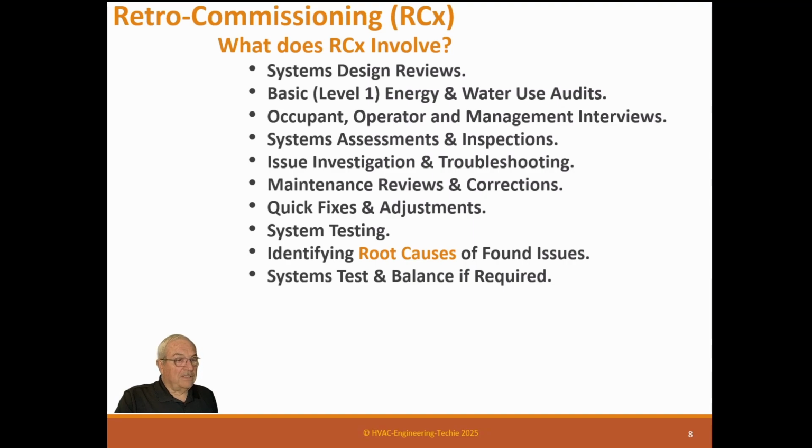System test and balance. If you're not a test and balance person, you need to have someone on your team who is, because you're going to do that. I guarantee you there are a lot of test and balance issues. Test and balance is one of those things that doesn't stay static. If you move something on the air side, it affects something elsewhere. And if you get 5 or 6 years of that, it's totally out of balance. So we will not rebalance everything, but we will fix what's not working.